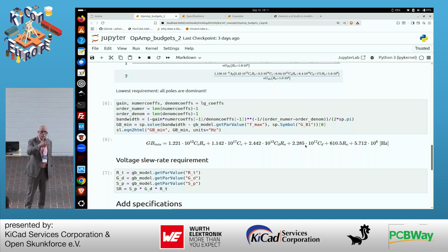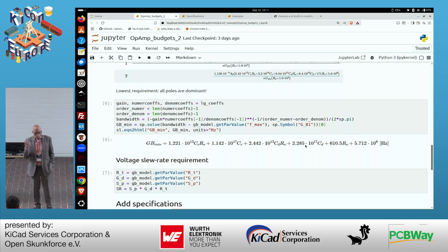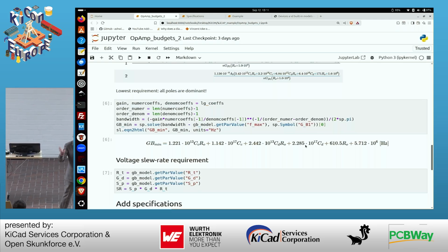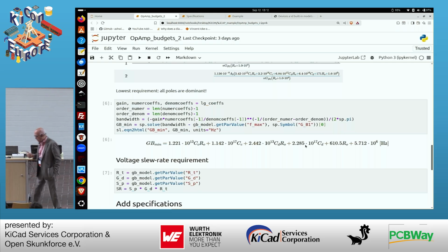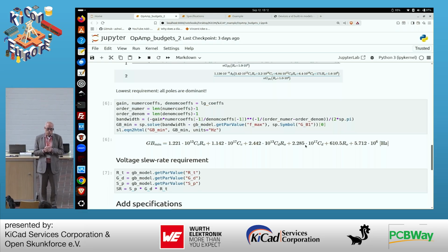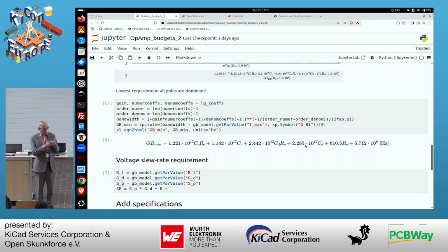We have an example now running in Delft for the masterclass of this course, which is a low noise amplifier, a chip amplifier with dual loop feedback. So you have 2 loops of feedback making a nicely low noise defined input impedance, for example. And then you have requirements for the gain, for the input impedance, and for the noise. The gain should be exact, the input impedance should be exact, and the noise should be better than a given value.